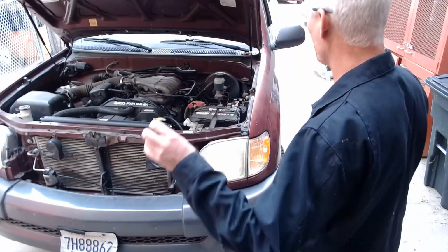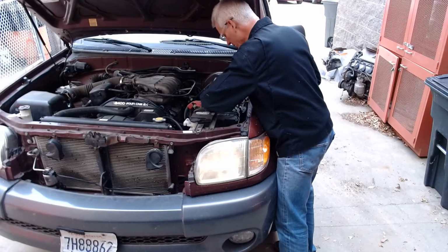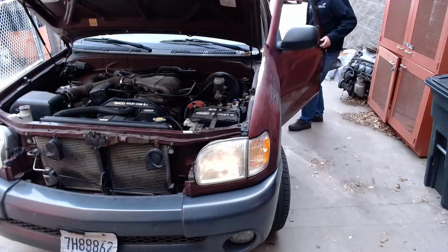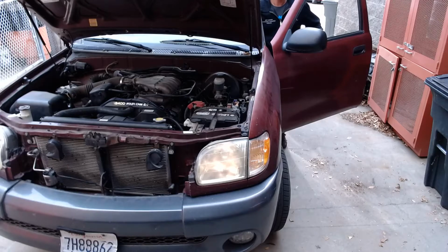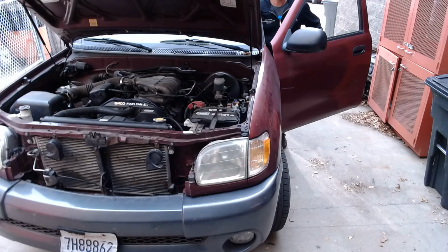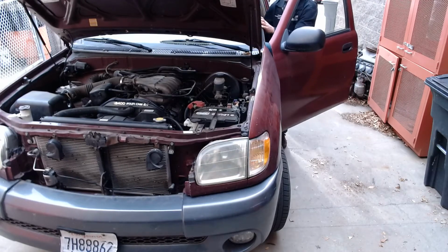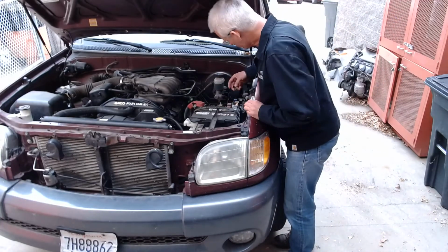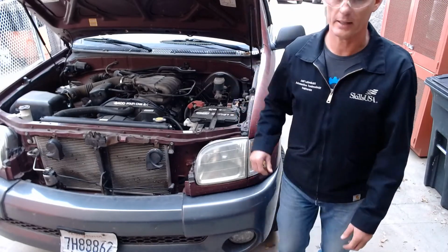It was supposed to kill power to the circuit opening relay. So pull the relay out. I'll leave it there. Let's try cranking the engine. See if it'll crank. Okay, so that won't allow the engine to crank. So that kills two functions. So we haven't been able to find an isolating function. So let me try again. Hang on a sec.